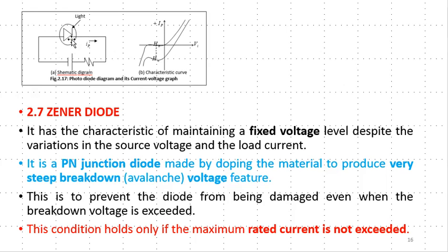And in reverse bias mode, ideally we are not supposed to have any flow of current, but because of this light falling on this junction, it creates pairs of electrons and holes. Thereby when they move, they create a current. And this graph is now telling me the influence of the intensity of the light on what? The amount of current. Now if you look at this, this is H0, where I have the lowest intensity, and the amount of current is crossing the zero line. When you keep on increasing to a certain value, the reverse current is increasing very much along the negative axis because of the increase in the light intensity.